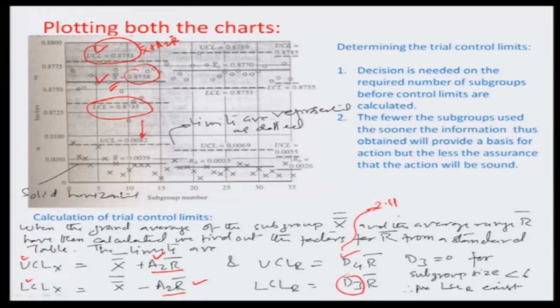But therefore, you can actually calculate the R bar and the UCL in this particular zone, and now all you need to do is to actually independently record the different X bar values. These open dots, for example, are those X bar values, and the moment it goes beyond control, you will see one value going out of this particular UCL or LCL. So, there is a very good real time indication of the process happening and how to control it.